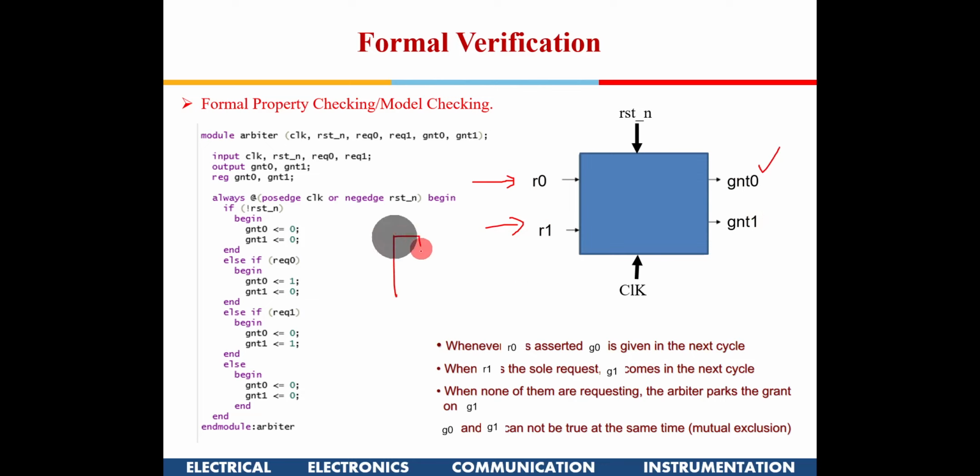You understand what an arbiter is? You have a microprocessor, and suppose there are several devices wanting services from it, for example your mic and your keyboard giving inputs. The microprocessor has to take on that task and produce the results. All of them simultaneously can't communicate with the microprocessor, so in between you will have an arbiter. You can call it a priority interrupt controller. All the requests from external devices come to this arbiter, and it tells the microprocessor which one to take on.